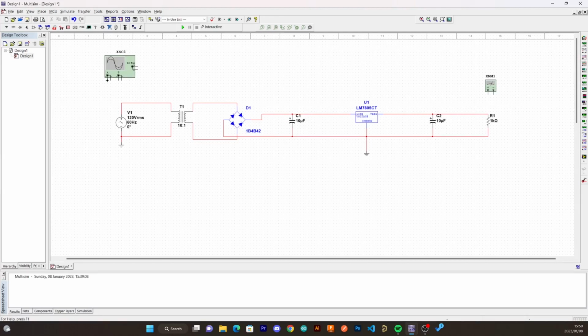So to measure on our AC, we need to connect two junctions. We'll connect the first channel. The plus side, you connect to the positive side of your supply, and the negative side, you connect to your ground part. So we have connected this oscilloscope to the input.